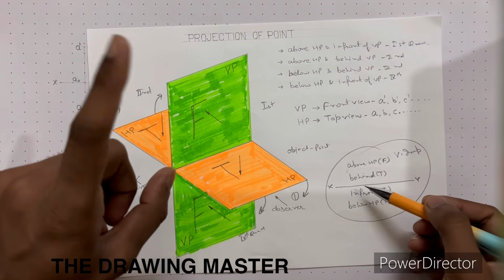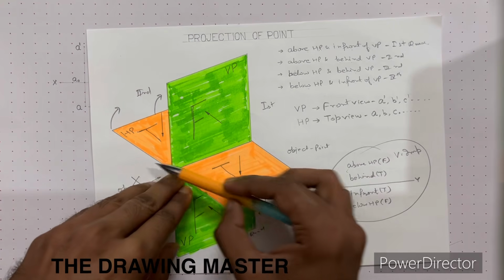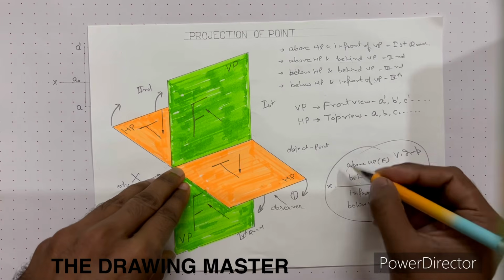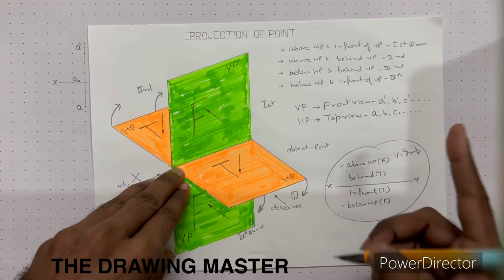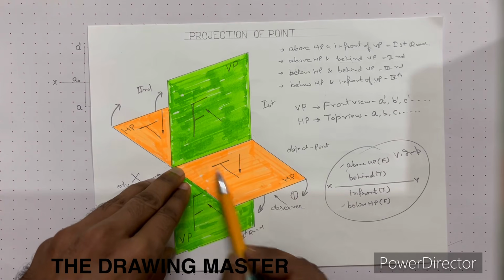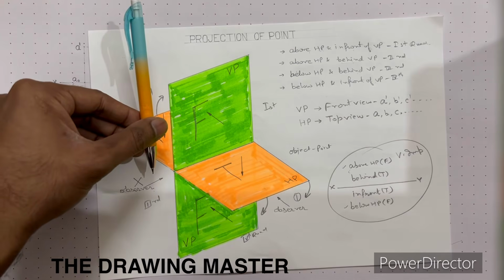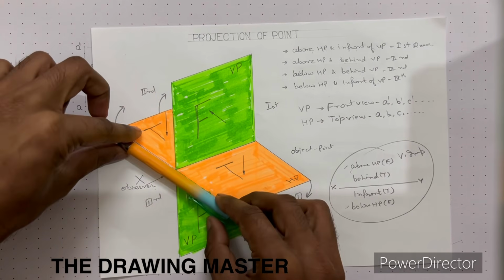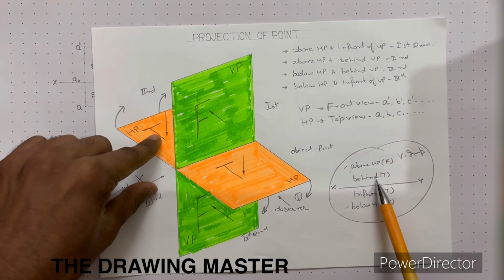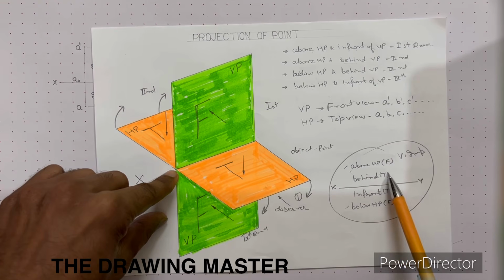I am repeating. Above HP means above the reference line. Below HP means below the reference line. And it will always be front view, visible from front. In front and behind will be visible from top view. So after the rotation of plane, behind will be above the reference line and in front is below the reference line, and is always top view.